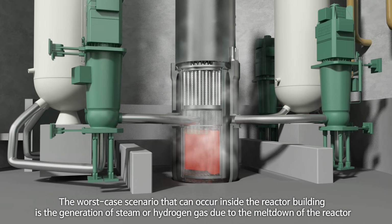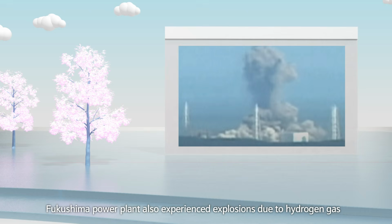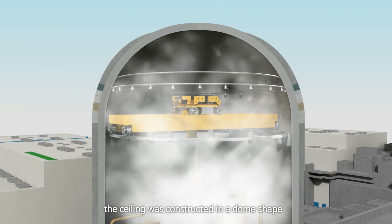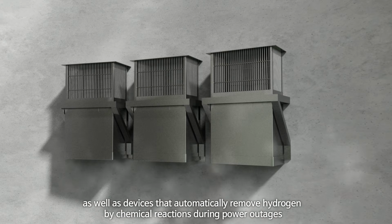The worst-case scenario that can occur inside the reactor building is the generation of steam or hydrogen gas due to the meltdown of the reactor. Fukushima Power Plant also experienced explosions due to hydrogen gas. To withstand the pressure caused by newly generated gas, the ceiling was constructed in a dome shape. To remove hydrogen gas, there are devices installed using electricity to generate sparks and remove hydrogen, as well as devices that automatically remove hydrogen by chemical reactions during power outages.